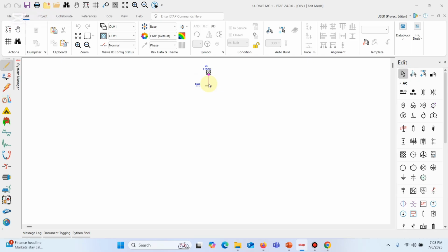For us to know that it is able to connect once we remove the arrow, the bus bar must also turn pink. So, for example, I take it down more, you can see the bus bar is changing color, black, pink, black, pink. So, once it is pink and I click on it, we now have a connection. We've successfully connected the power grid to the bus bar.